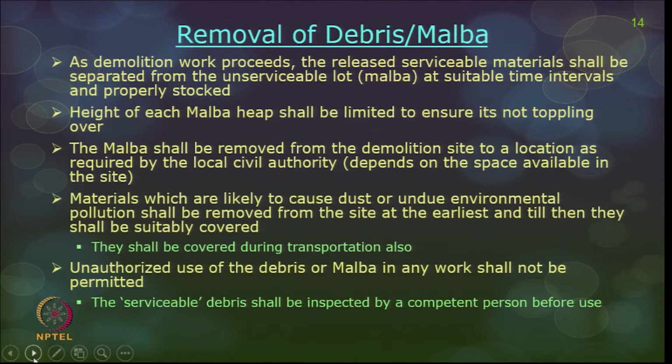So, during transportation also these dangerous substances or Malba should be closed and covered. Unauthorized use of debris or Malba in any work shall not be permitted, and even the serviceable debris which is used for recycling should also be inspected by a competent person before it is taken for use.